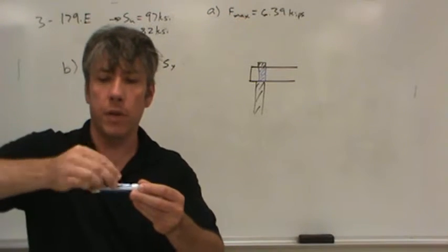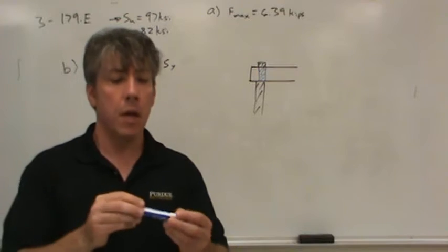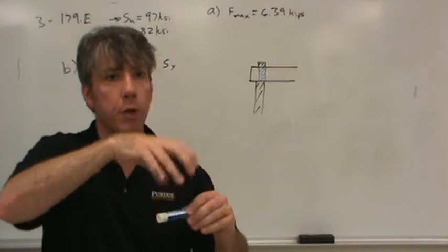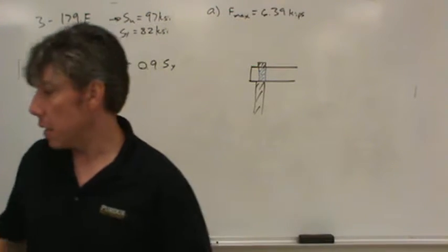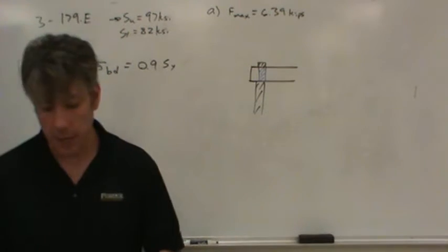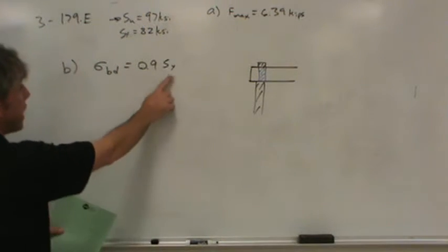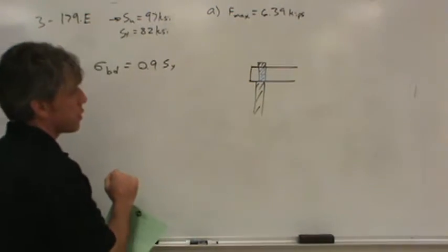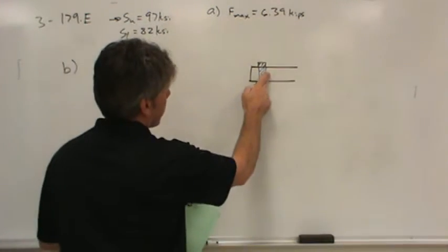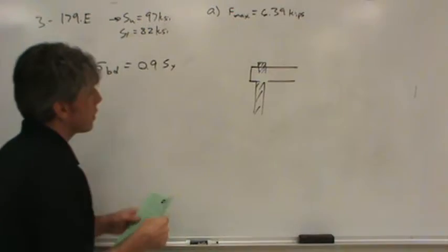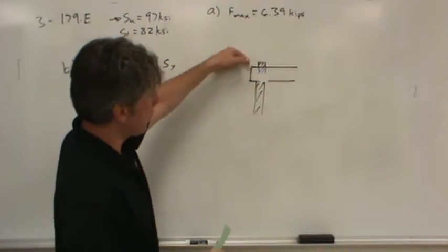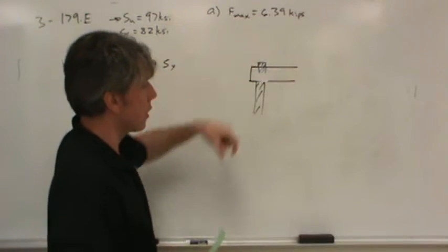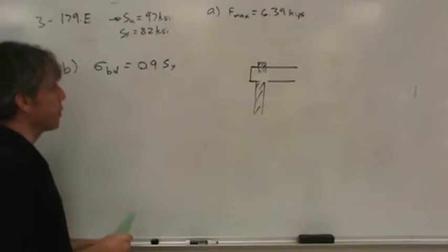And that force on the surface, like in the Glasgow Tower, could cause the surface to actually move, to deform, right? And so the recommendation we have here is that only 90% of the yield strength be used to calculate how much stress could be applied to the surface. And my drawing's not very good really. I'd rather have it like this so that you see the areas wrapping around 180 degrees like this to hold onto that pin and push on the surface.